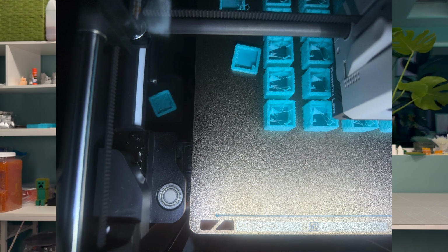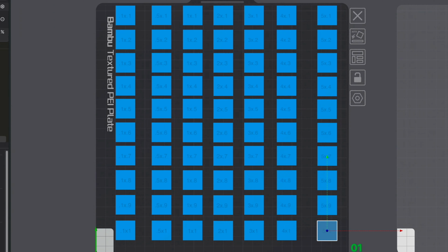With the issue of collisions with other objects sorted, a new issue popped up. Some of the cubes are coming off the build plate entirely, sometimes so forcefully that the cube was actually shoved off the edge, or yeeted, as the young people would say 5 years ago. This took several attempts to finally figure out, but the first hint was that it was only impacting the cubes with the 0.1 point distance setting and the larger thickness settings.